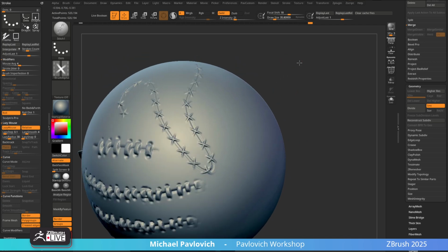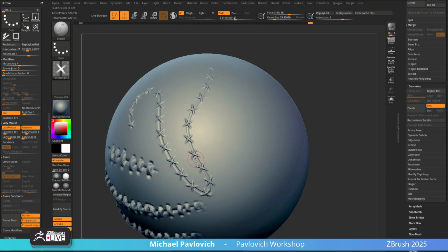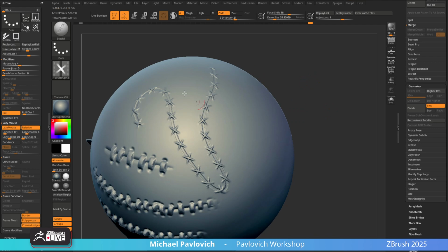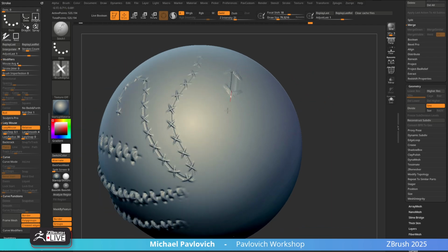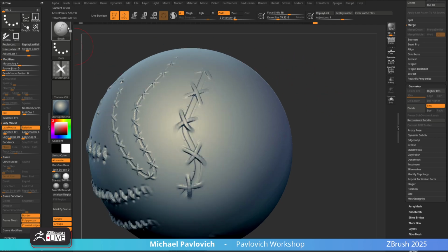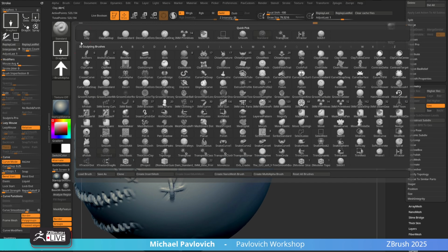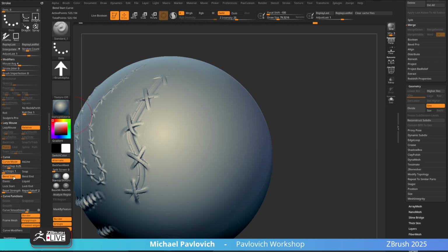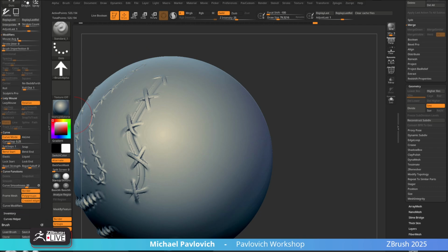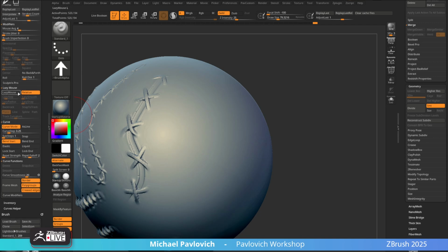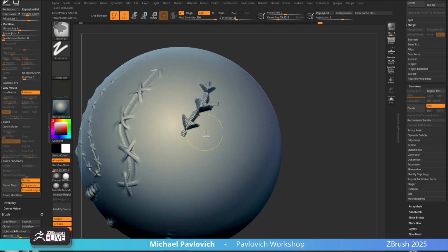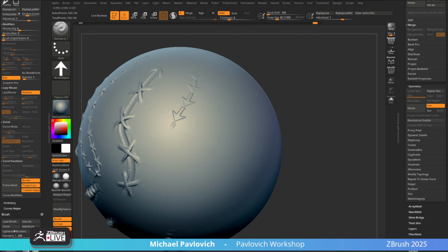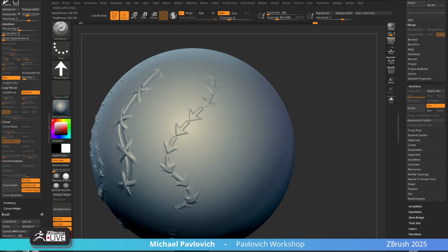So now you can create stitches. Obviously you can't change the stitch type or the height or the color of the stitches, all that good stuff. But if you're in ZBrush and you want a 3D print, then this is what I would do. You could just start with a stitch brush and swap this alpha out, or you can take your standard brush, clone this off, switch here to dot stroke, turn on roll. It's all coming back to me. Stroke. Roll distance of 1, and then we want curve mode off. And then it will just roll. Let's turn that Z intensity way down. There you go. And now we're just rolling that alpha through in a stitch way.